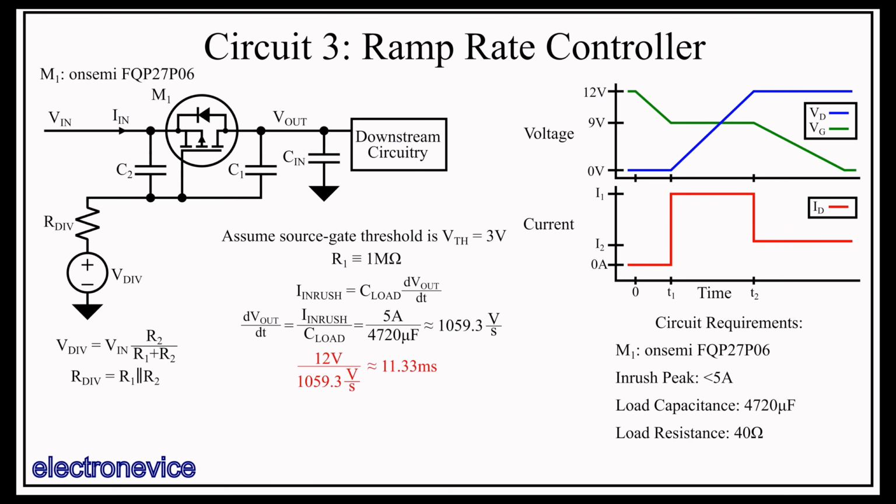While this is true, the resulting circuit will very likely be slower than our estimate due to the assumptions we have made, but even if it isn't, we can reassess in test. So let's go with a target of an even 1000 volts per second, a nice round number. So to design this target, we need to know IDiv, which involves setting RDiv, and we need to set C1.